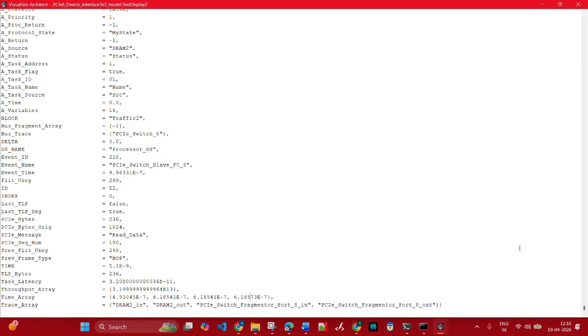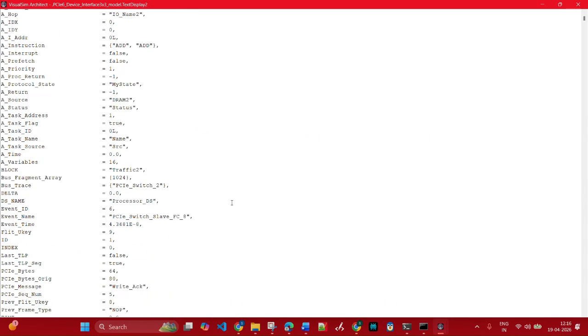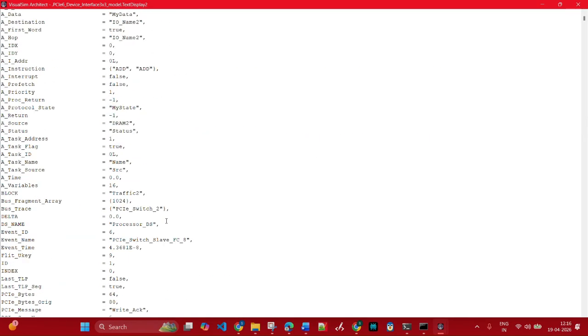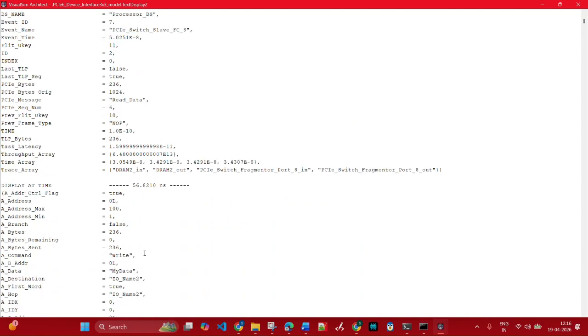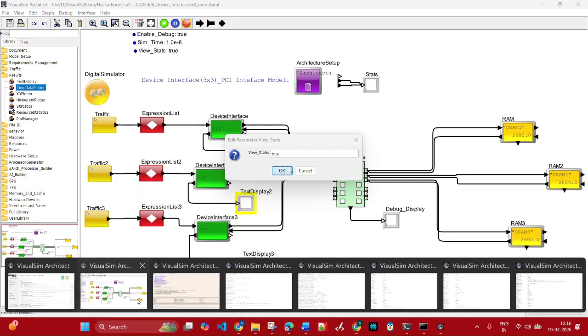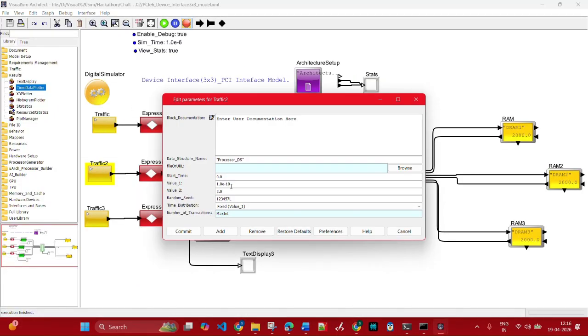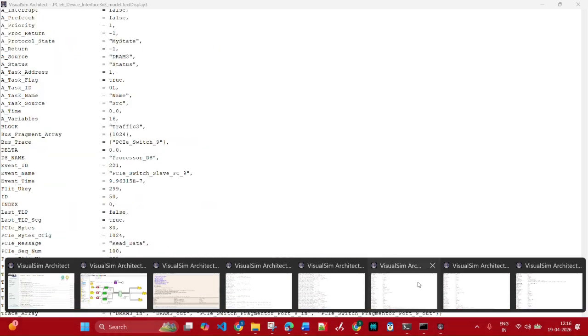We get the whole throughput from issuing. From 43 nanoseconds it has started issuing the transaction. The next issue happened at 50.25 nanoseconds. So it's a 7 nanosecond difference or something like that, 7 nanoseconds for each. That's what I'm configuring here for TG2: some value, so it generates that much TG rate. So it is issuing at this rate.